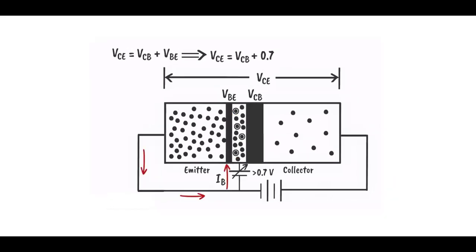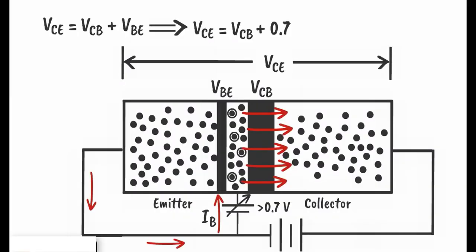These electron-hole recombinations contribute to the base current. The remaining 98% to 95% of free electrons cross the collector-base junction due to the kinetic energy gained from the electrostatic force of the base-emitter voltage. These excess electrons in the base region can easily cross the reverse biased collector-base junction, because these free electrons appear as minority carriers in the base region, and the reverse biased collector-base junction does not oppose the flow of these electrons into the collector region.